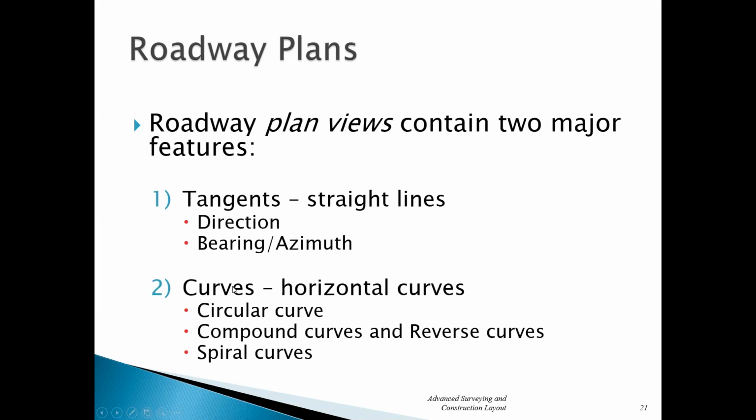These curves are typically referred to as horizontal curves because they exist in what plane? What am I saying when I say horizontal curve? That would be in like plan view. Okay, which is the horizontal plane, right? So yeah. These curves are projected into the horizontal plane, and your tangents are in the horizontal plane as well.